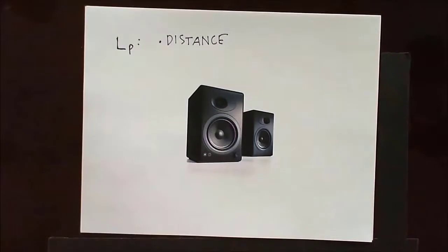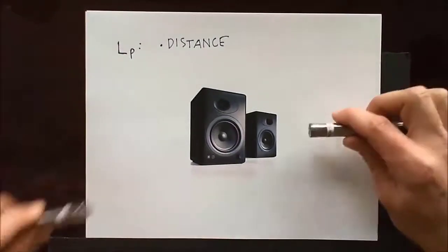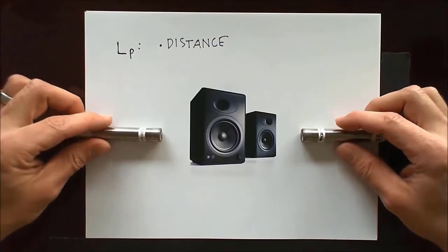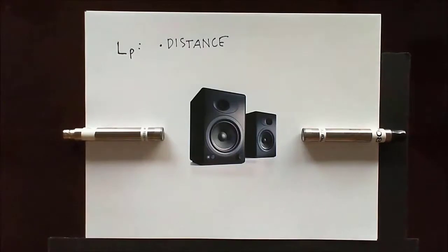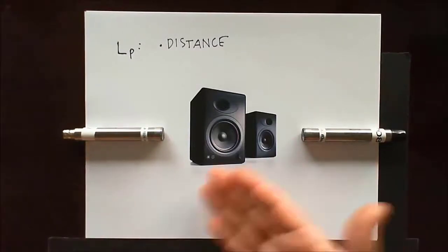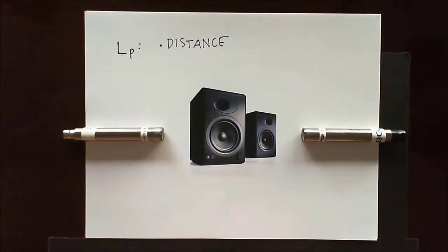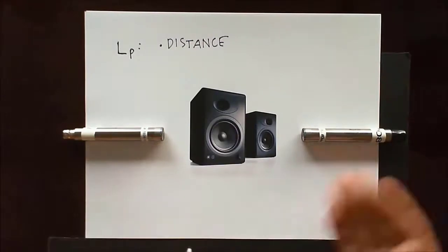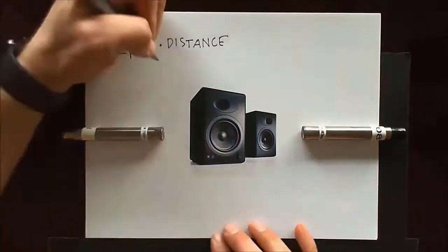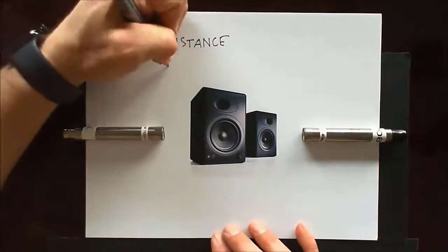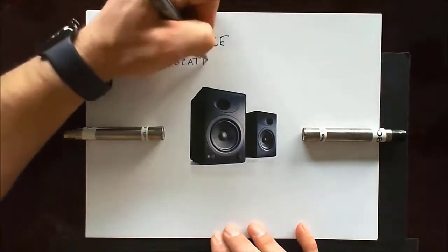Okay, so let's say we have another choice to make. Let's say these two microphones are equally distant from the sound source. They're, let's say, 1 meter away in this case, but one's sort of in front of the speakers and one's sort of behind the speakers. Will we measure the same value here? No. Speakers are pretty directional devices. They're designed to broadcast noise in one direction. And so this guy over here I would expect to be louder because it's in front of the speakers than this guy over here that's behind the speakers. And so we see sound pressure is also a function of location.